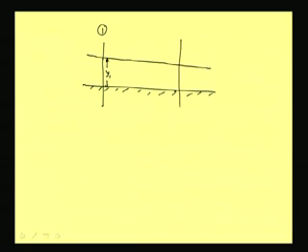then at the downstream section 2 our depth is not changing, it also remains y1, that means the depth is not changing. Now the discharge coming is, say, q, and we know that q is equal to area into velocity. This is a very well-known relation, the continuity condition.